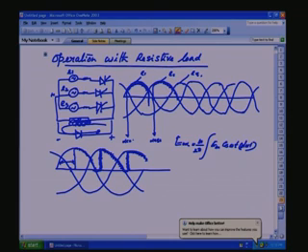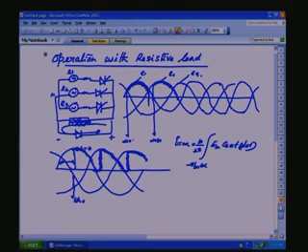So, the lower limit, if omega t is equal to 0 here, for the cos omega t waveform, will be minus pi by m, then plus alpha. So, alpha can vary from 0 to here, for symmetry operation.